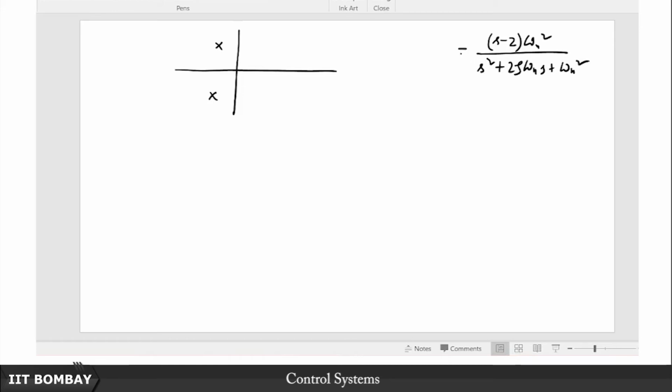So when you are making k positive, then this overall thing is negative. Okay, so or if you absorb this negative sign in the k, right? So if you now put this k here and get this k to absorb this negative sign, then it's basically studying the complementary root locus of this transfer function. So that's how we transform this problem into one of a complementary root locus.